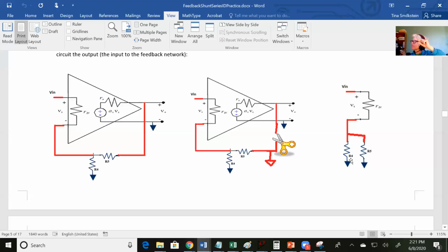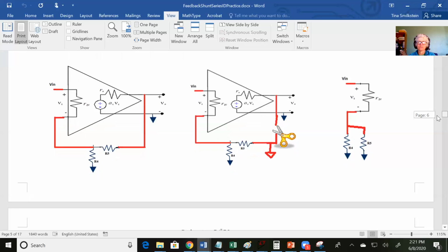If you give an amplifier a smaller input, it's that difference that gets amplified, and now you get less gain. So if R4 and R5 are too big, this voltage divider gives you much less gain. So that's one problem you can have.